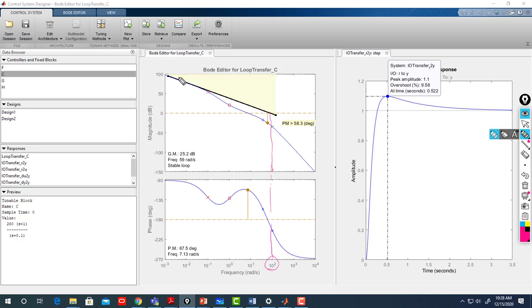But at the end, this is 20 decibel. So this 20 decibel crossing it here. 20 decibel per decade. This is essential because it keeps the same slope. So you can do it using this design requirement. I recommend not to, because designing the requirement in Bode diagram is not as familiar as in the case of root locus, and so it may take more time. But it's good to know about it. But I don't recommend going this way. Okay.